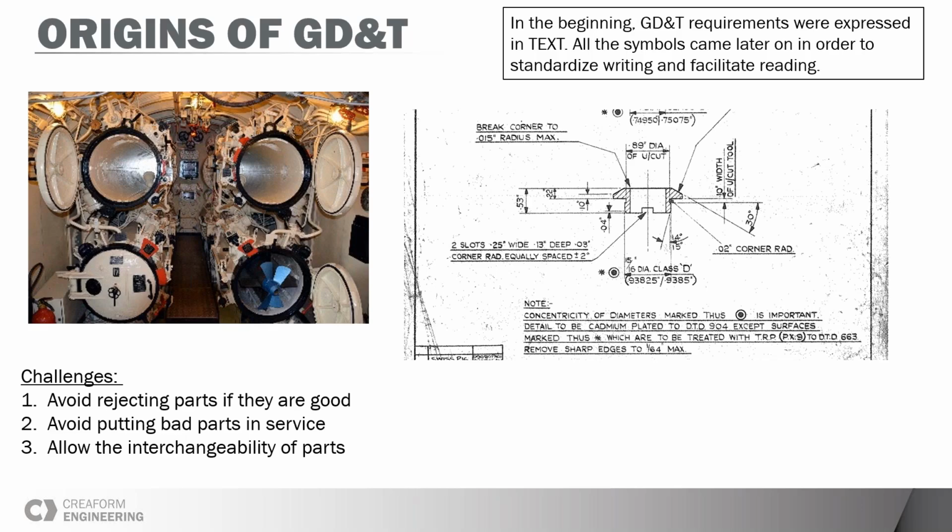But the most interesting thing we can learn from that book is that it didn't even mention GD&T symbols. The book talks about the concepts, but when it's time to describe the geometry on the drawing, they use text and notes. I think there are two things we can learn from that. One, the concept came first, then the language appeared to ease the communication of all of that. And second, when you are unsure about the perfect way to describe something on the drawing, a well-written note can still be used.